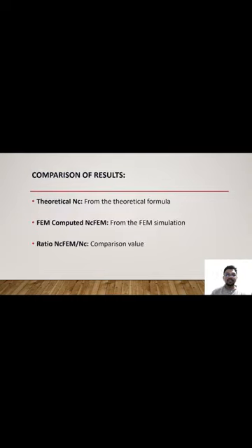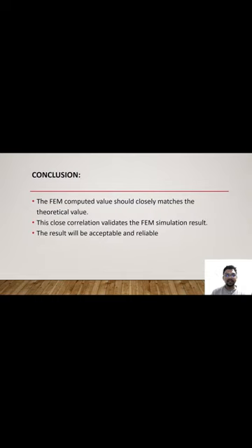For the comparison of results, we have to compare by taking the ratio of Nc FEM to Nc. In conclusion, if the result is almost equal to 1, or closely matches the theoretical value, then this correlates to the validation and the result will be acceptable and reliable.